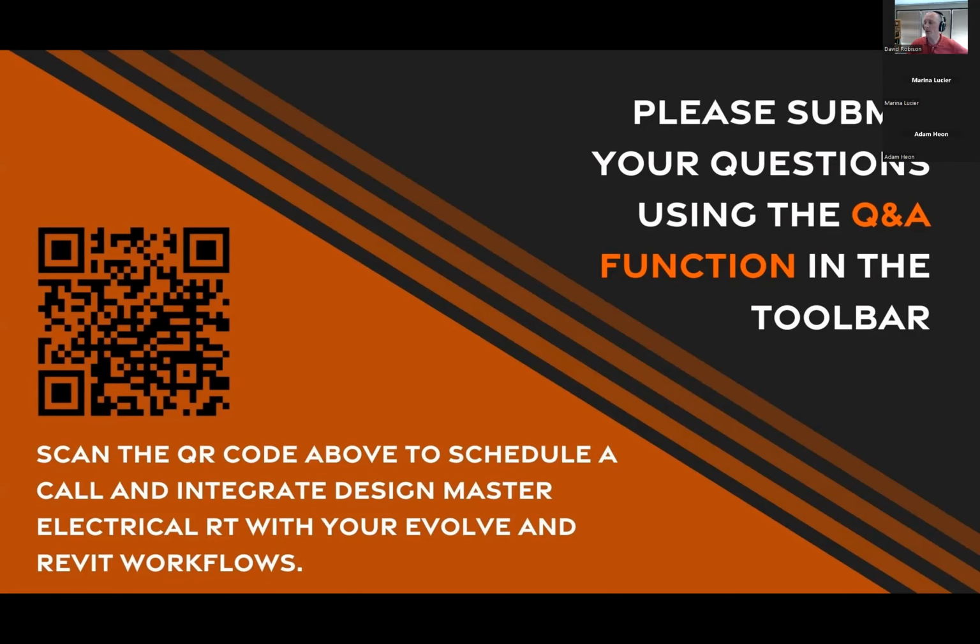The feeder lengths are then carried over to Evolve. So the ones that we calculate do show up in the conduit run schedule as the estimated length somewhere over here. You may have to right click on the header there and say column chooser. Column chooser, thank you. Where is it? There it is, column chooser. And double click there on estimated length. There it is. Yeah, so we fill in our values and I clicked OK, so that disappeared because that wasn't doing what I thought it was.